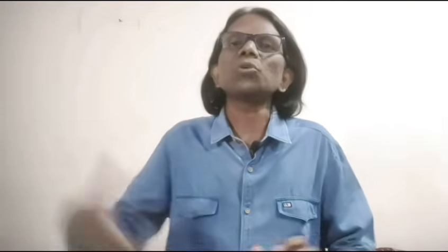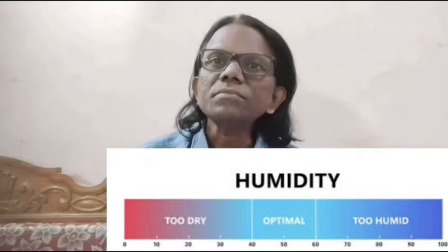Actually, frozen shrimps or frozen fish at minus 20 degrees centigrade, we can store for 24 months. Unfortunately, within 6 months or within 1 year, the products get freezer burned, or the products encounter dehydration and severe burns. We can extend the shelf life to about 24 months and we can reduce the electricity bill by 10 to 15%, which is generated by running the cold storages. Evaporator cooling coils running time also we can reduce. Relative humidity plays a crucial role.